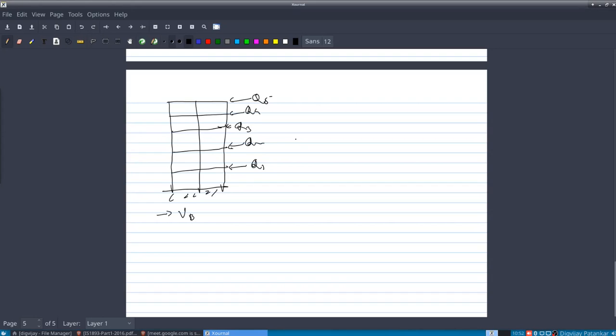Now do the regular analysis, any method you want, finite element method, or since the system is simple, you can use classical methods as well. And due to these Q1, Q2, Q3, Q4 and Q5, find out what the internal forces in beams and columns are, that is bending moment, shear force and axial forces. And for those bending moment, shear force and axial forces, design the member as well as provide appropriate ductility using ductile detailing by IS 13920.